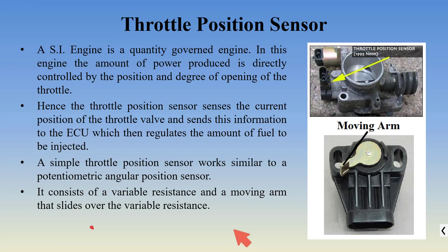In a voltage divider circuit, there is first of all a fixed voltage. Here is 5 volt, here is ground. Between these, here you connect your sensor. This is your sensor. A sensor is basically, in a large number of cases, a device whose resistance changes with the changes in external conditions.